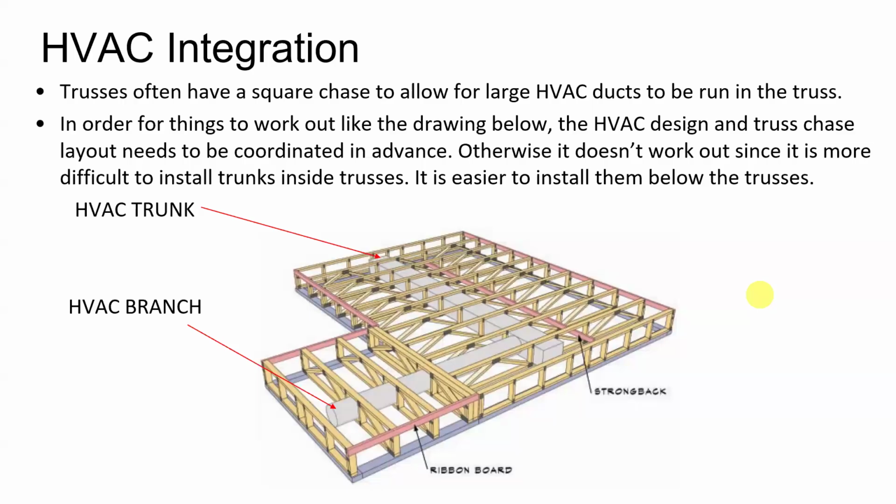Okay, so this is the best case scenario. If you get your trusses all laid out properly and your HVAC people are online with it, in theory, they can get their ducts in. So this is called a trunk line, just like a tree, and this is called a branch, just like a tree. Typically, you can get your trunks and branches in the trusses. Now, the problem is